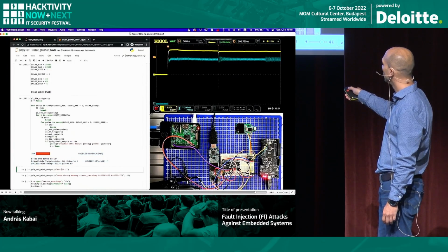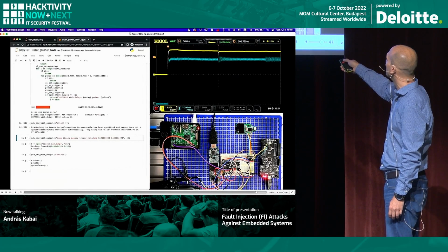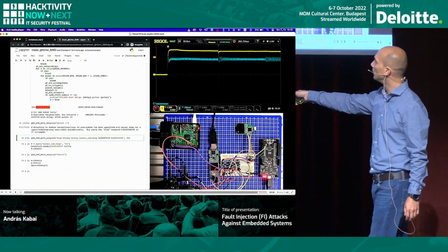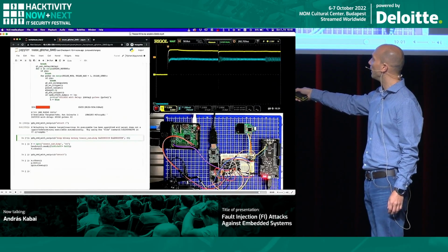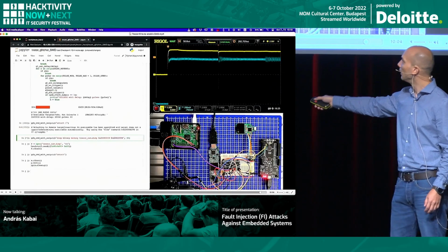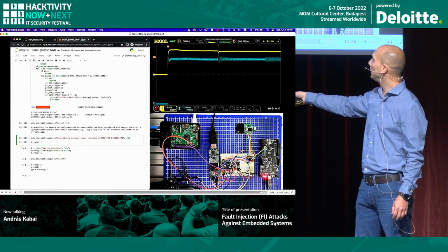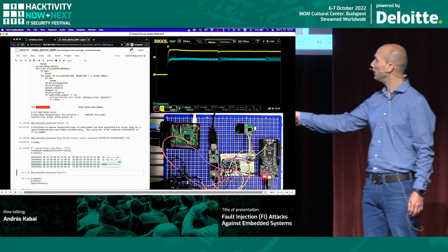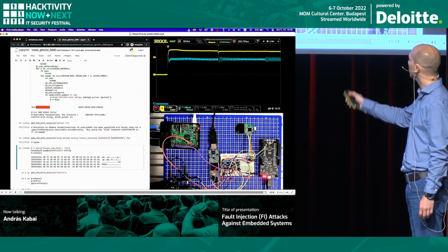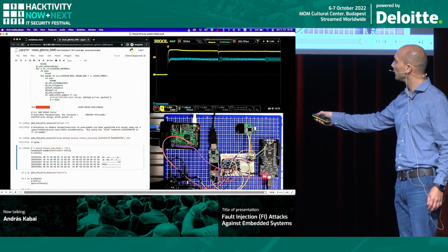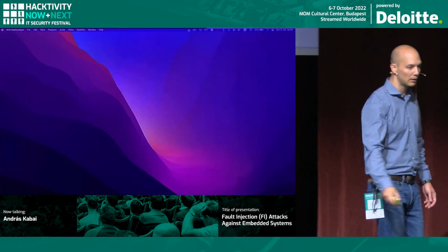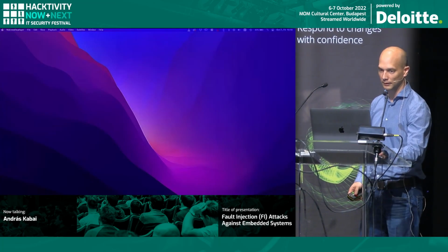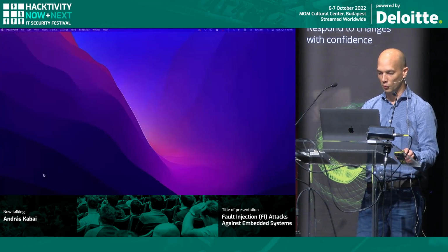on the target. So now the command execution stopped because we attached our debugger to the target. Using the GDB session, I'm now executing the dump binary memory command, which basically dumps out the memory content. And what you can see is loaded back from the dumped file. This is nothing else but the USB class memory structure that you can also find, for example, in the Trezor's code.